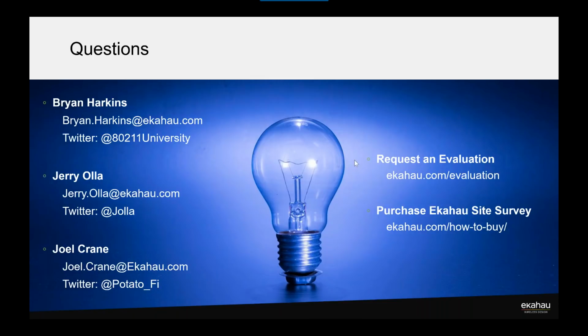Will choosing wider channel support impact the resulting RSSI or SNR values? It's not really going to affect the received signal strength values, but it will let you know the channel width at which the client has to operate. So if you have a client that is capable of that, then you can plan for that a little bit better. If the AP can do a 160 megahertz wide channel, but your client can only do 40, that's not going to affect the AP at all, because the AP is going to be able to step down and do a 40 megahertz wide channel with no problem.